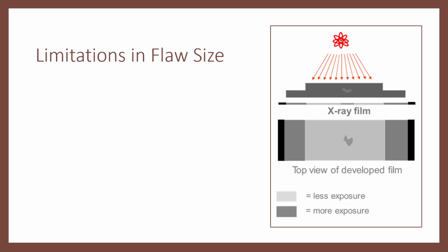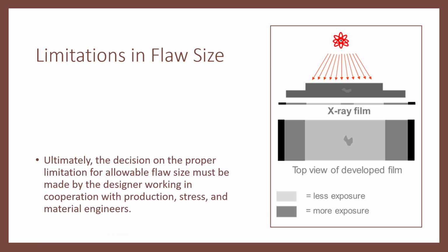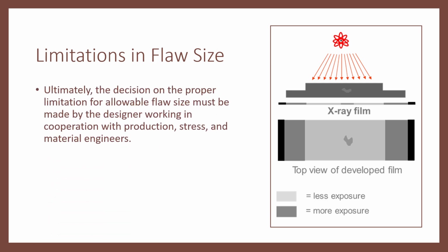One of the things we need to understand about non-destructive testing is the limitations in flaw size. The decision on limitations for allowable flaw size has got to be made by the designer with the production, stress, and materials engineers. How big of a flaw can we have in this part before we have problems, before things fail?